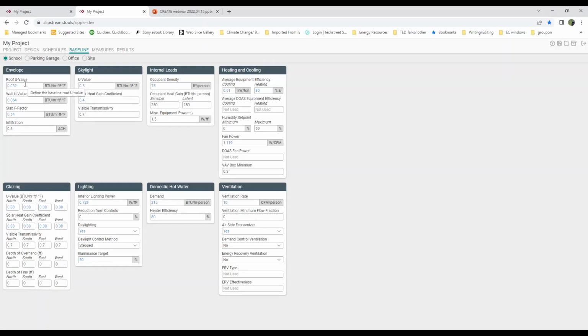The best bet in that case might be looking at the drawings, if they have access to the original set of drawings, and then pulling out the building envelope factors from the original specifications. And, you know, it might have degraded a little bit over the course of 40, 50 years. So set back these values to be more reflective of where the building is currently at.